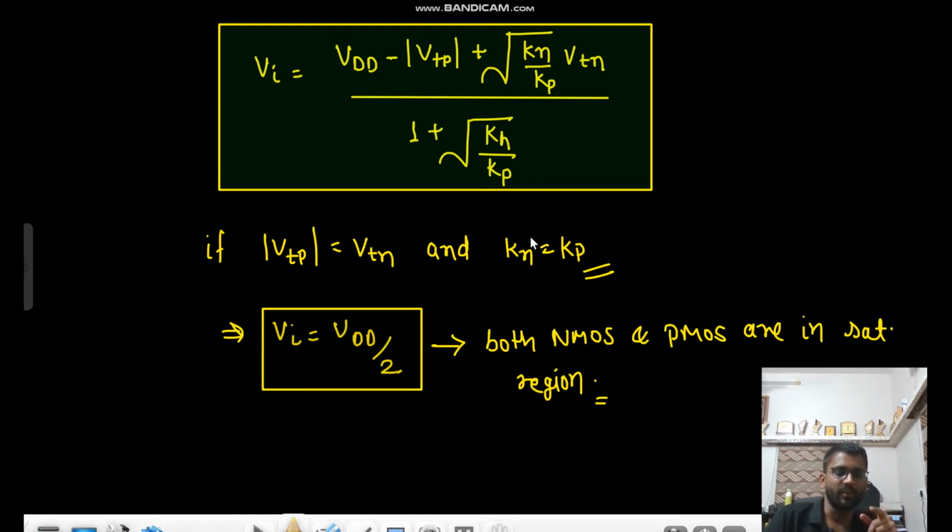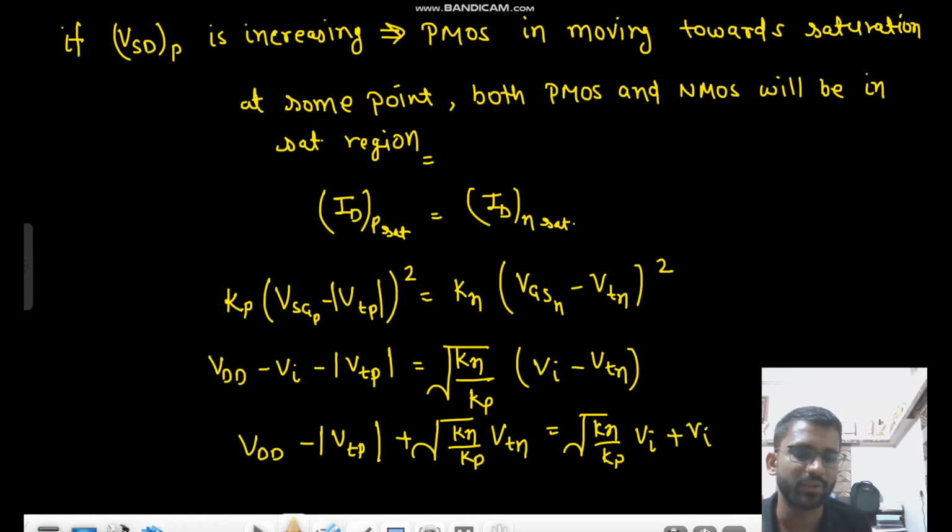5.5 upon 1.5. What is that? That is greater than 2.5. That means your switching threshold value will increase. So that's how you can change the value of switching threshold, by varying the value of Kn and Kp. Okay. So these questions are very much asked. So you should know this concept.